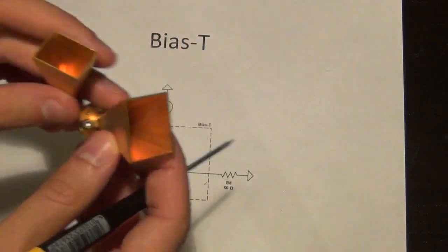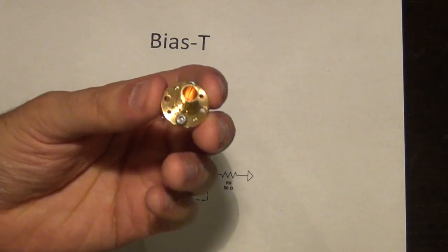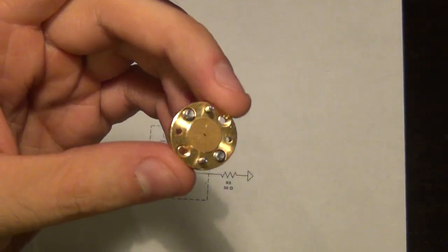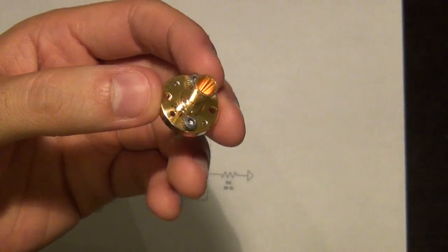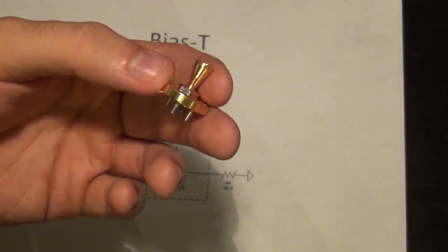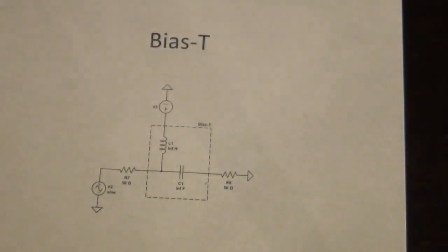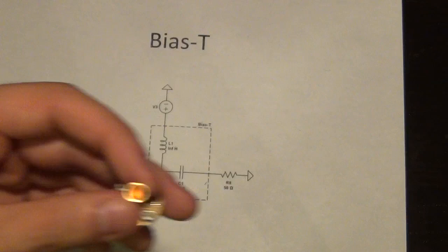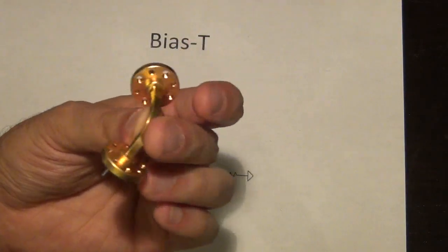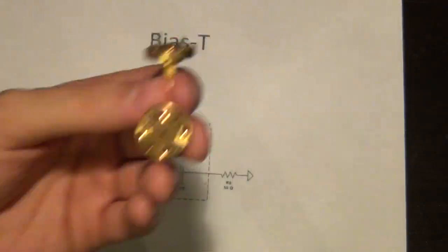But you can go really crazy up in frequency. Check out this guy. This is another waveguide, but look at how small that opening is. This is a 325 gigahertz antenna. So this thing will actually radiate out 325 gigahertz if you put a 325 gigahertz signal through it. So again, for very specific measurements, not many people build circuits in this frequency range, of course. And you can have all kind of bands, and this is an E band, you can have an H band, and so on and on, all kind of waveguide pieces.